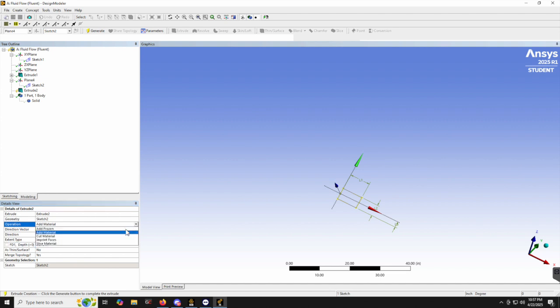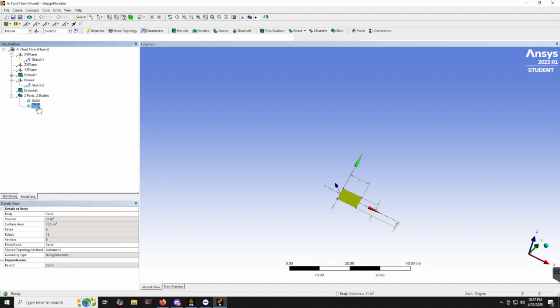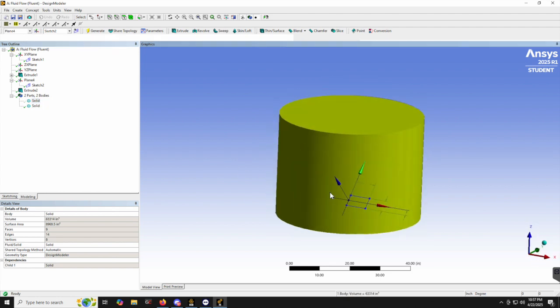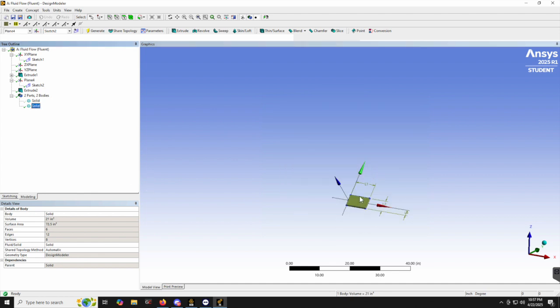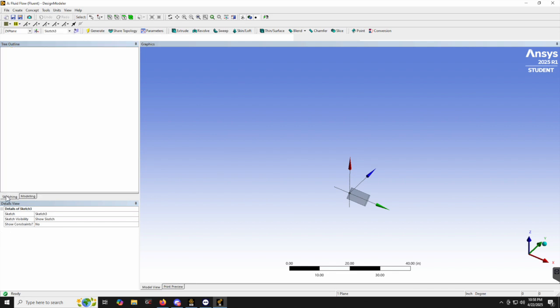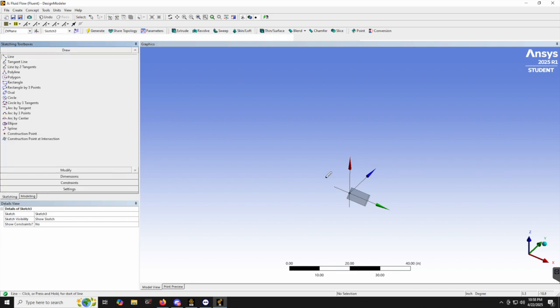And instead of adding material, I'm going to slice material. When we generate that, we will be left with our fin along with the tank with the fin subtracted from it. This blade I'm going to pattern. So I'm going to start by creating another sketch on this XZ plane with just a line that we can use for our pattern.